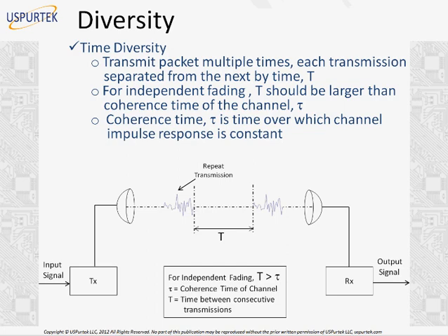You know, because of this environmental fading, the fading can happen not just because of reflection or multiple signals received, but the channel parameters can also change. If it is a rainy day, you will have a different channel response. If it is a sunny day, you will have a different channel response. Or from time to time, they can change. So we define a coherence time, the time over which we know for sure that the channel impulse response is constant.